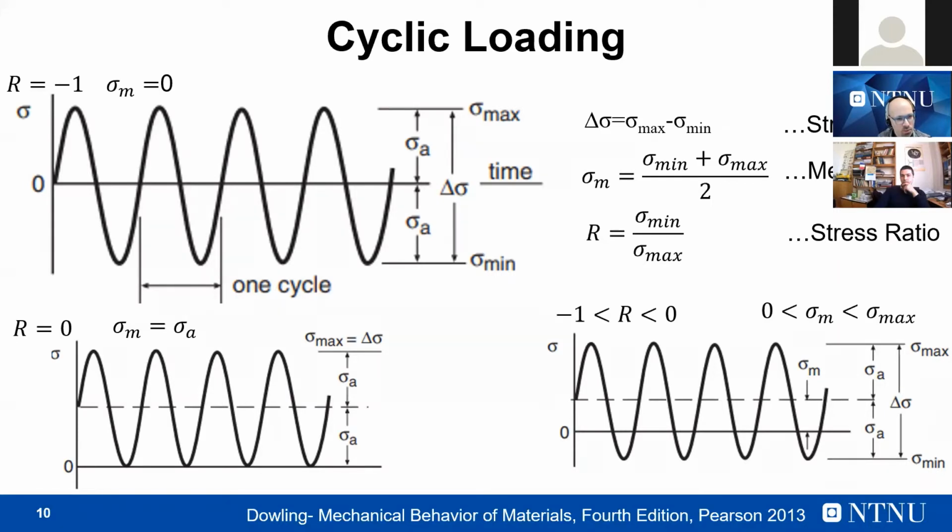And today we need to speak about fatigue, so we need to have a common language. And I want to introduce some important consideration about the symbols that we use. We apply a cyclic loading to a component, and what is important for fatigue is the amplitude of the cycle that we are applying and the mean stress value of the cycle, and these are the two most important points that we have to consider. R, which is defined as sigma mean divided by sigma max, is called nominal load ratio, and is important because it is considering the effect of the mean stress on our cyclic loading.